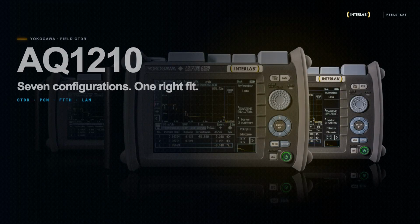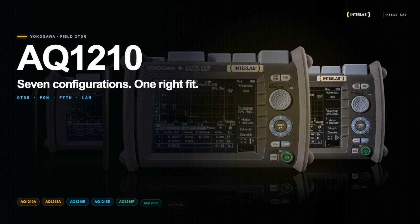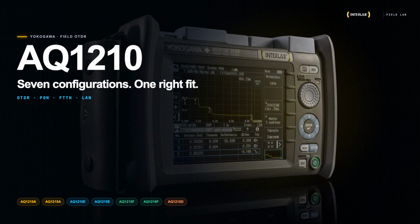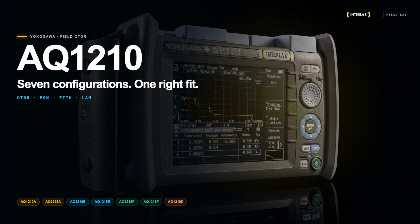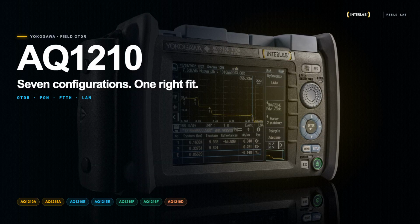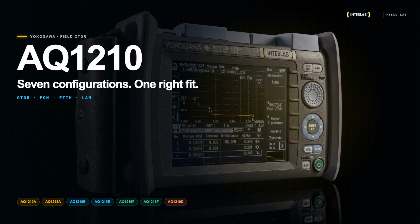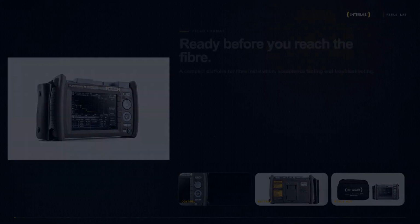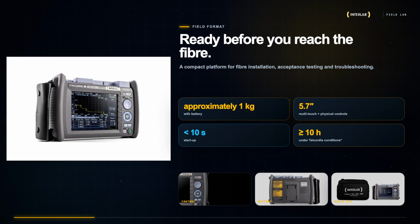One OTDR for everything? In this class, that is the wrong question. The Yokogawa AQ1210 family includes 7 configurations for dark single-mode links, live fiber, demanding passive optical networks, and environments combining single-mode and multi-mode fiber. The real question is not whether to choose an AQ1210, it is which AQ1210 fits the network. Every version uses the same compact field format, designed for fiber installation, acceptance testing, and troubleshooting.